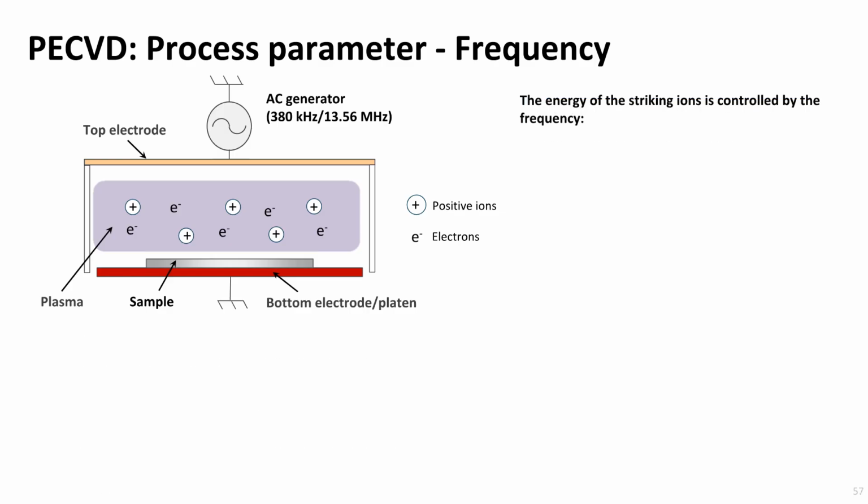Well, the deposition process starts with generating the plasma by applying an alternating voltage. The voltage accelerates electrons that collide with neutral gas species, which create ions and neutral radicals. These radicals are very reactive and partially act as the precursors for the deposition. There are two power generators connected to the system. One running an AC potential at 13.56 MHz, and the other running at 380 kHz.